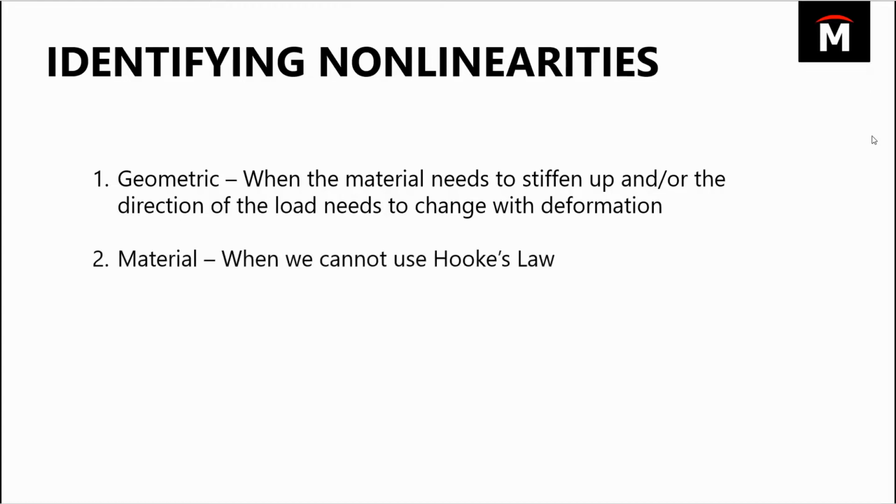Of course, the material is a big reason people might move to nonlinear or even Simulation Premium. If you're working with composite materials, maybe something that has a layup, could be carbon fiber or fiberglass type composition, that's going to be available in the Simulation Premium license. But really any material that we can't consider linear, something where if you put in 100 pounds and it bends an inch, 200 pounds does not mean it's going to bend 2 inches. Well, that's a nonlinear response. So there's a lot to look at when it comes to materials.